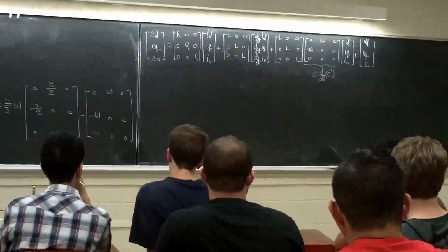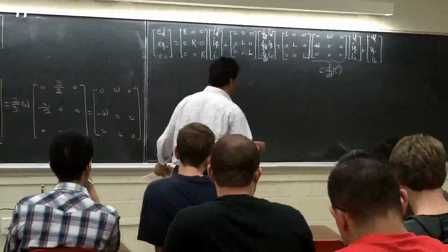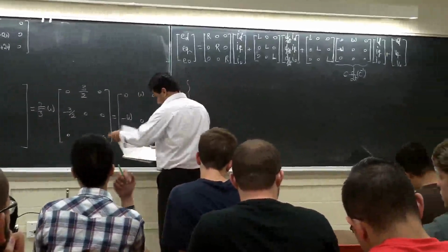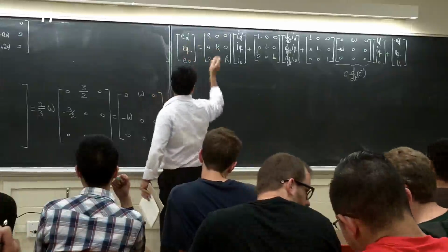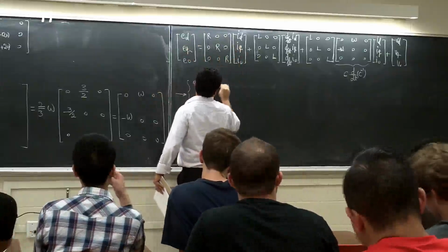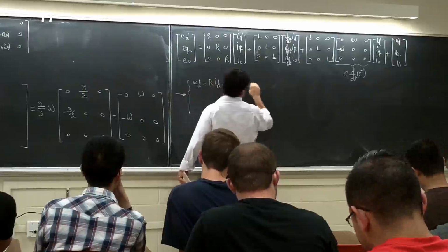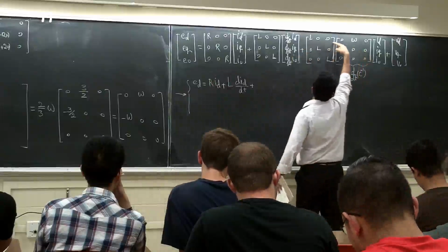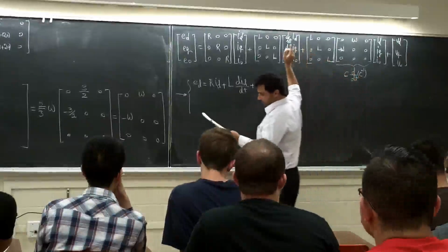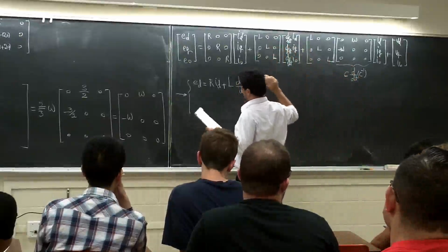Now let me just take it out from the matrix form. I don't care about the O, to be honest, because this is a balanced system. I don't care about O. So if I rewrite the equation, it's going to be like this. E_D is going to be R I_D plus L dI_D over dt plus this one, this one times this. You do this one, it's going to be plus L omega I_Q, plus V_D.